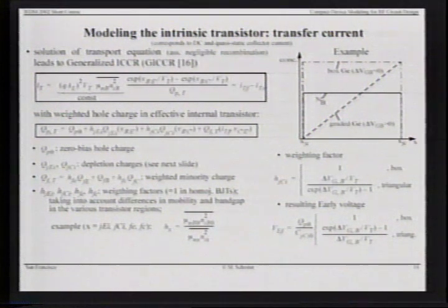one of the fundamental equations we have in bipolar transistors. We have this equation in every bipolar transistor model. It's a single piece, continuously differentiable equation for the whole operating region. It's not like MOS where you have to piece things together.